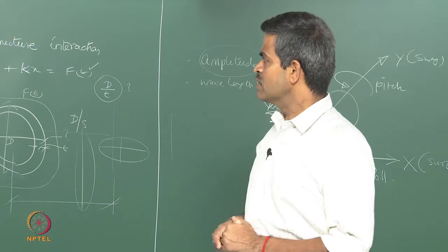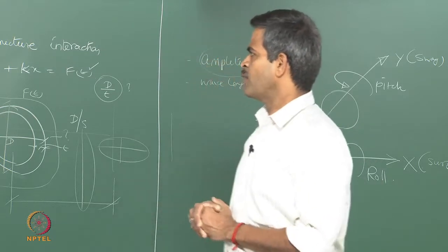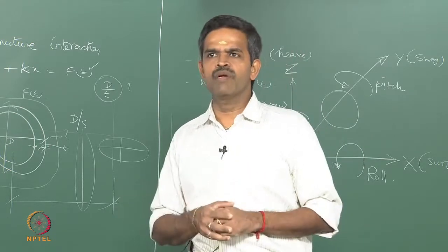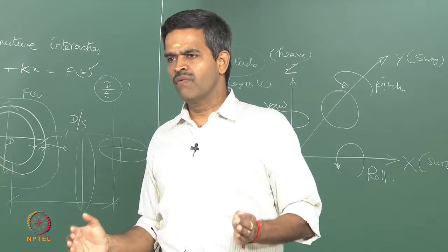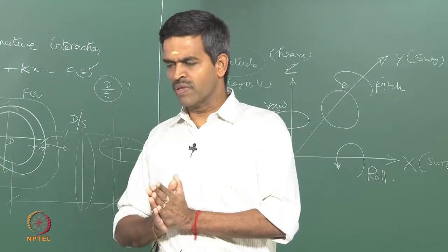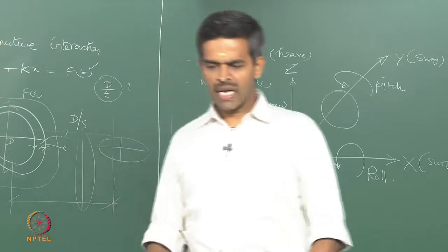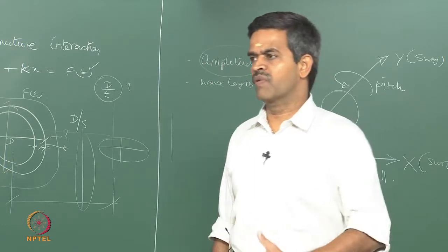Damping is important in limiting excitation of the structure, we all know that. Offshore platforms are normally designed so that natural frequencies are well beyond the bandwidth or the dominant frequency of dynamic excitation. We know that because we have already seen a curve where the design curve says my dominant frequency is in a specific range, whereas my natural frequency is classically either very low or very high compared to the dominant wave frequency.